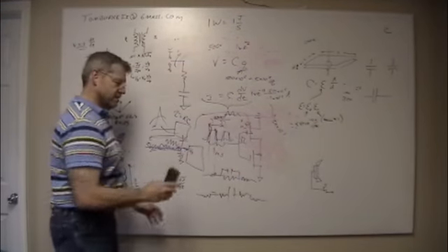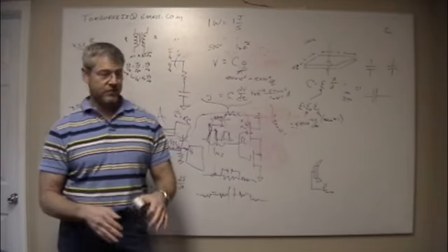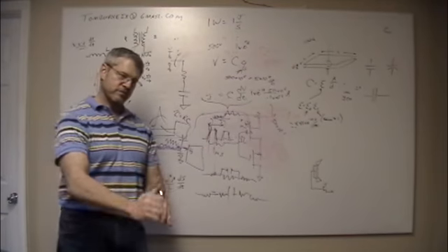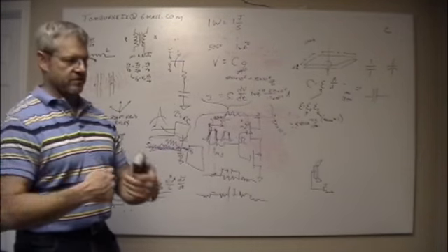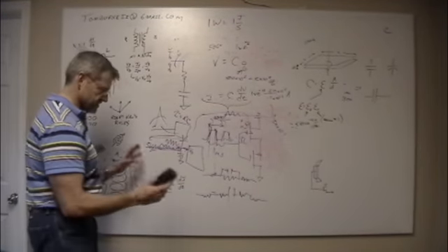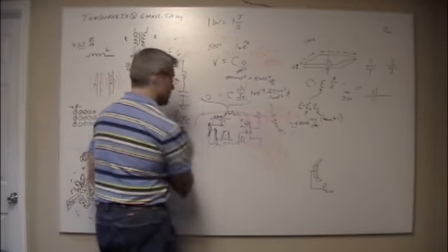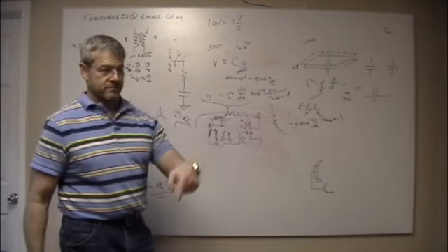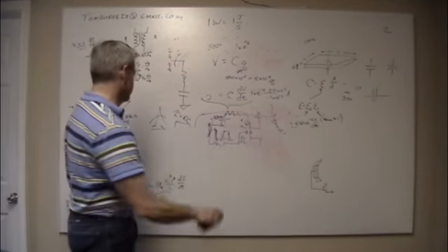And so when you're down at a circuit board level, you've got to be careful with your layout. You want high-speed signals. You want to put ground planes around them so that it protects them, and so that their noise doesn't leak out onto other things and do other stuff. So that's one of the practical uses, is to keep your power supply clean at the point that needs it.